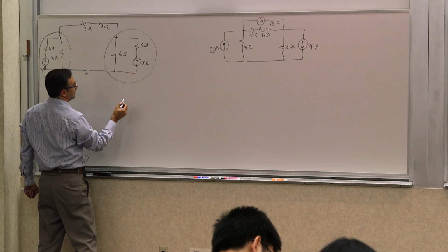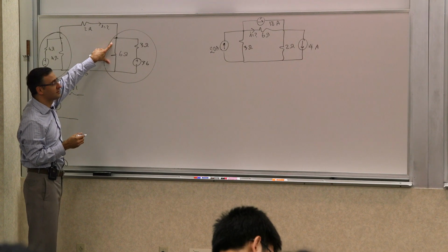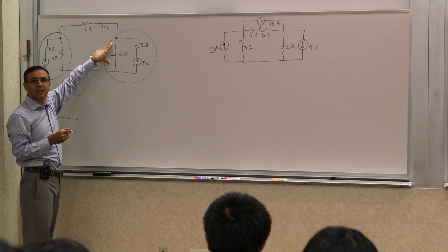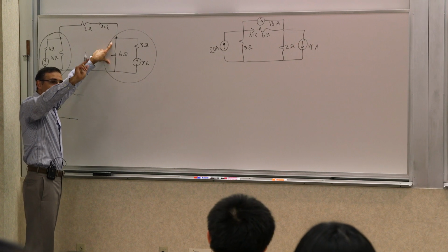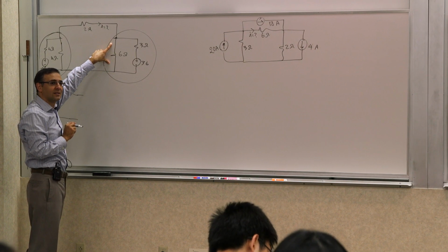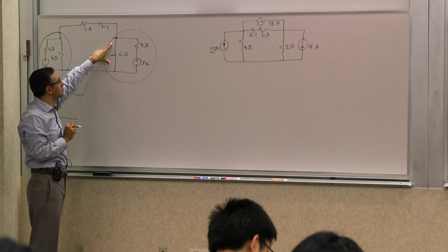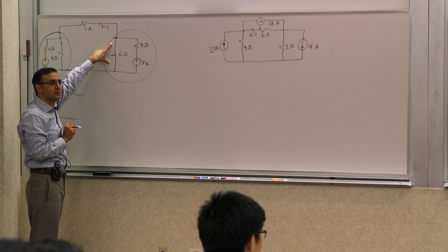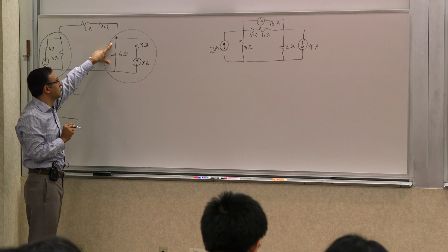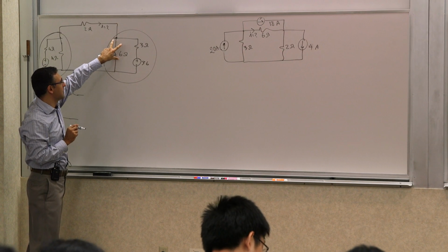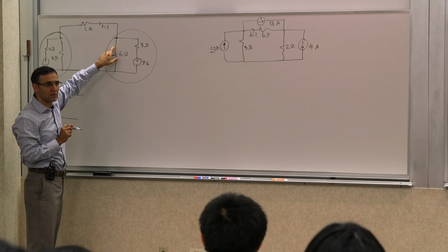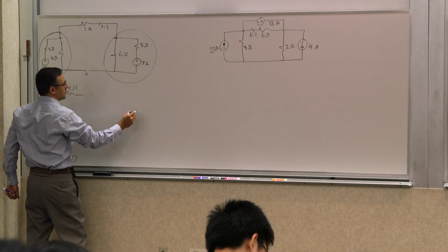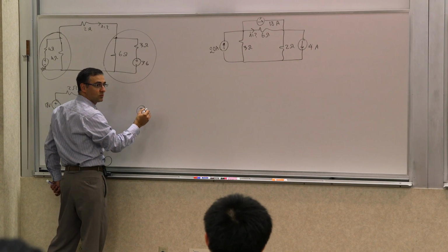How about this side? What is the voltage I will see across here? This time I'm going to ask someone who's next in that line, in the back, second row. Voltage divider. Uh-huh. 3 and 6. Right. The divider ratio is this resistor divided by the sum of the two. So it's 6 divided by 9, 2/3 of 36, which is 24, right?